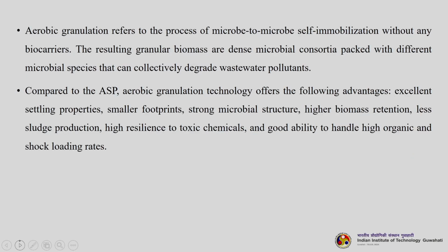So, what is aerobic granulation? Aerobic granulation refers to the process of microbe to microbe self immobilization without any biocarriers. There are no biocarriers here. The resulting granular biomass are dense microbial consortia packed with different microbial species that can collectively degrade wastewater pollutants. So, compared to the ASP, aerobic granulation technology offers the following advantages.